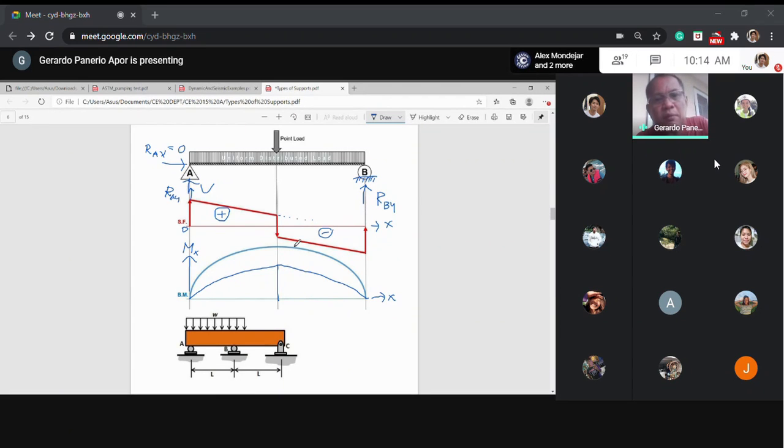see from the shear diagram that the point of zero shear is the maximum moment. Okay? Isn't that in your notes? So, aside from the sum of the areas in the shear diagram being equal to 0, we say that the point of zero shear is where the maximum or minimum moment is. There you will see whether it is a maximum or a minimum moment, whatever. So, you can see whether it is maximum or minimum. Okay.